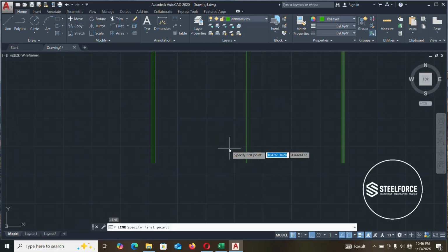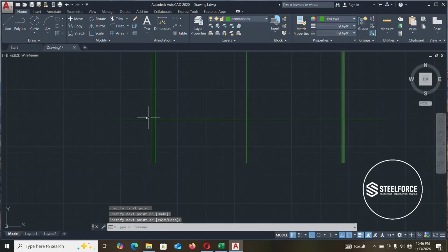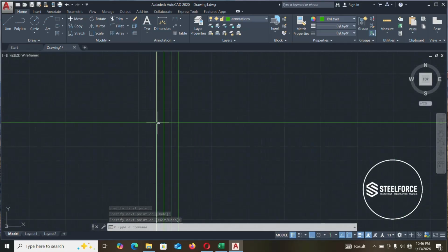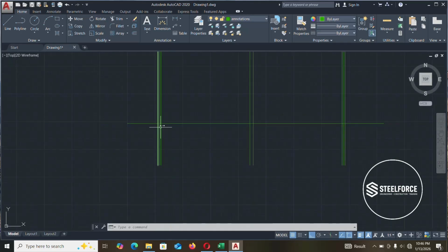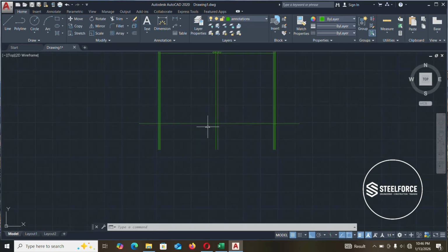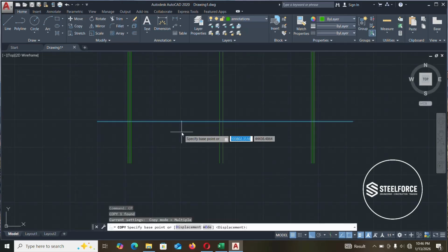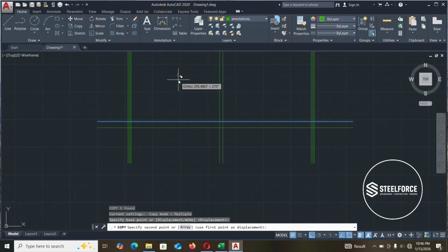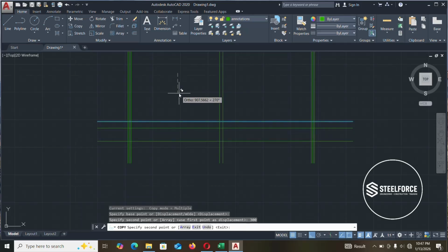So now we are going to draw a line from here to here. And we are going to consider the foundation of the wall. So we'll assume this is a strip foundation. So this side, you can copy this side and give it a hardcore filling of say 300 millimeters. Then another soft core filling of let's say 450 millimeters.